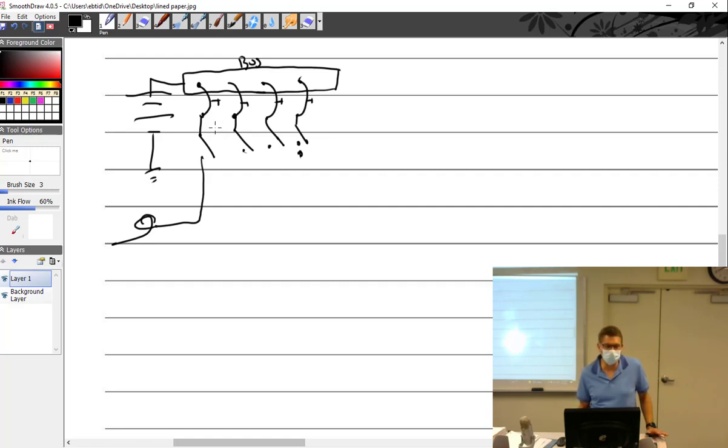So you can see what is in series? Well, in series, I have a circuit breaker. And by the way, circuit breaker, and I'll write this stuff down when we get to this in weeks ahead, when it's important and on your test. The circuit breaker is in series with the switch, which is in series with the load, but nothing else is in series with it. I can't run. So on an aircraft, you have wingtip lights and a tail light, 3 nav lights, right? So you have red, green, and white. Well, you're not going to run the red and then the green and then the white in series, because then if one goes out, they all go out.